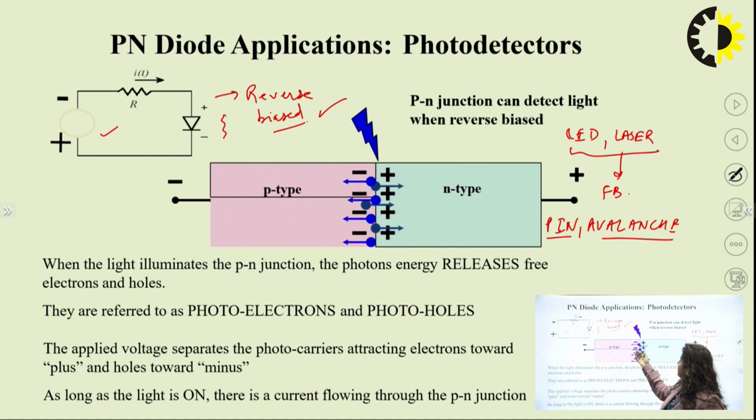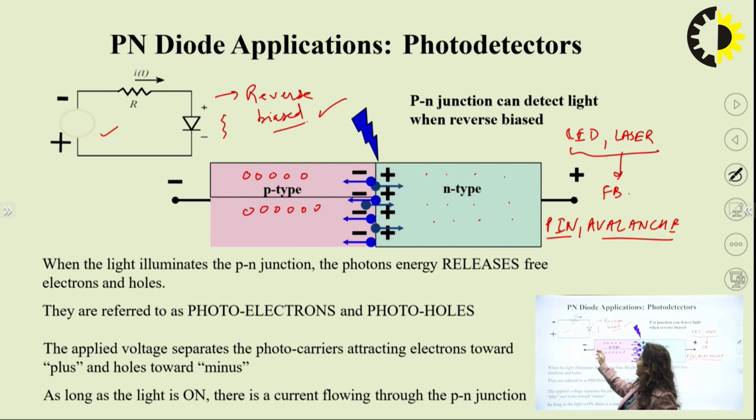In the diagram below, we have shown the p-type and the n-type semiconductor materials in close contact with each other. As we have discussed, whenever we provide biasing to a PN junction, in fact it is a reverse bias position. When we provide biasing, that is negative terminal to p-type and positive to n-type, obviously there are majority holes in the p-type, and majority electrons in the n-type. So the holes are attracted towards the negative polarity and the electrons are attracted towards the positive polarity. They get separated from the junction.